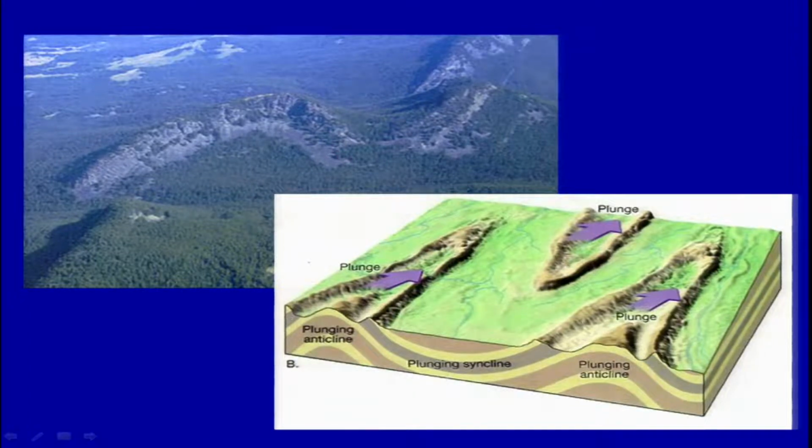So in the front, the sectional view, you may see that there is a fold, but in the top view or the plan view, you will not be able to see the fold extending, and it dies out somewhere here. Similarly, this fold dies out here and this one dies out here. So it is again important to understand whether the fold is plunging or not.